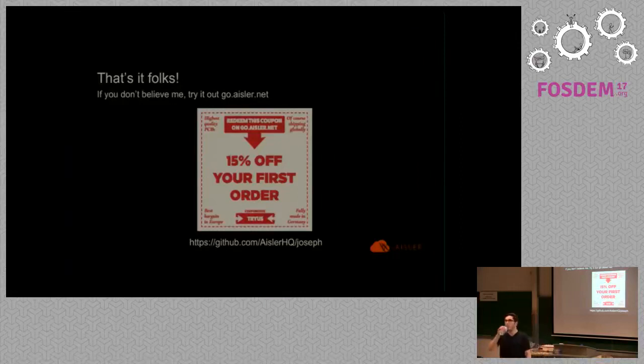Do you use the scripting also to check Gerber? I use it, for example, to count drills. You have to find single subjects to check on. For example, an idea of mine was to do some checking if the paste layer changes.